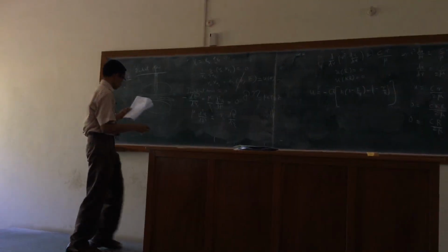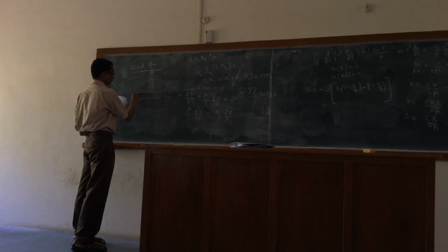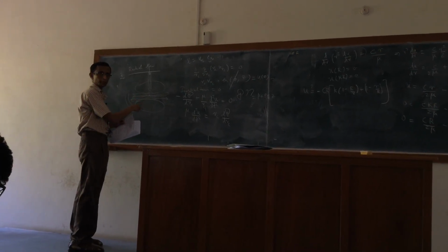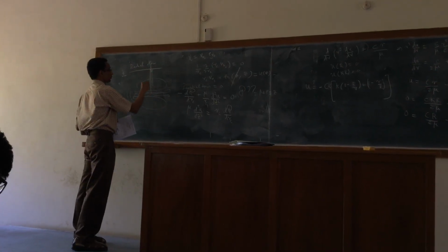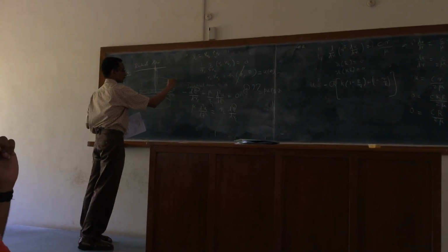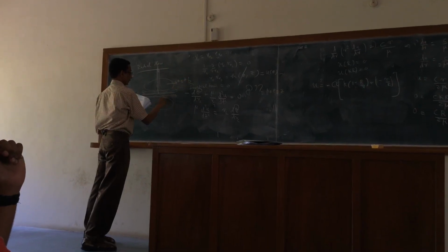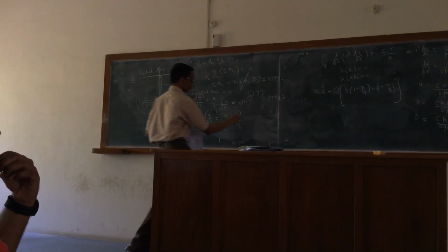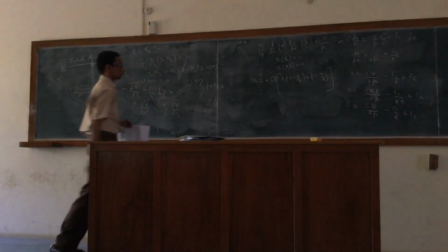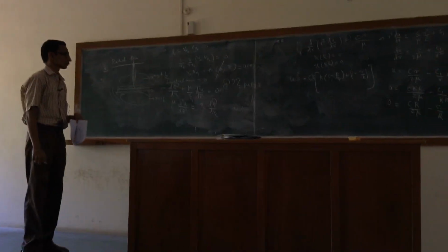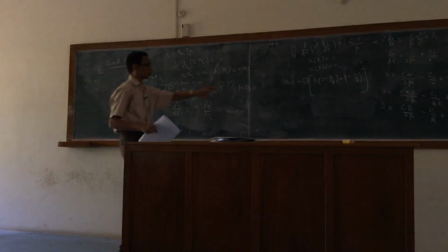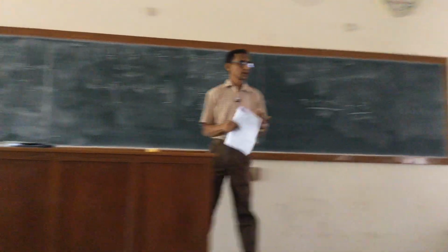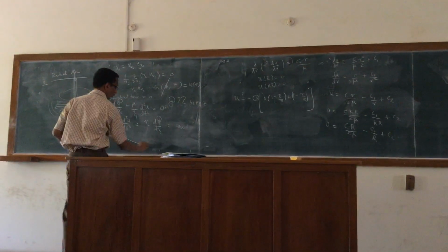According to the notation, you can clearly see that the origin here is the center point between the two plates. So the z-axis is what I have to fix. This corresponds to z equal to plus b, and the bottom plate corresponds to z equal to minus b. So clearly now this is a constant. You can easily prove that P plus rho times g times Z is a function of RC alone. That's what I'm calling the modified pressure. So this can be very easily solved.